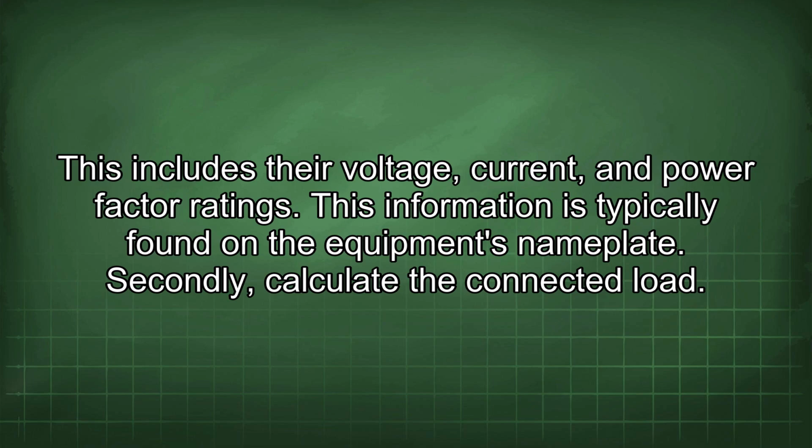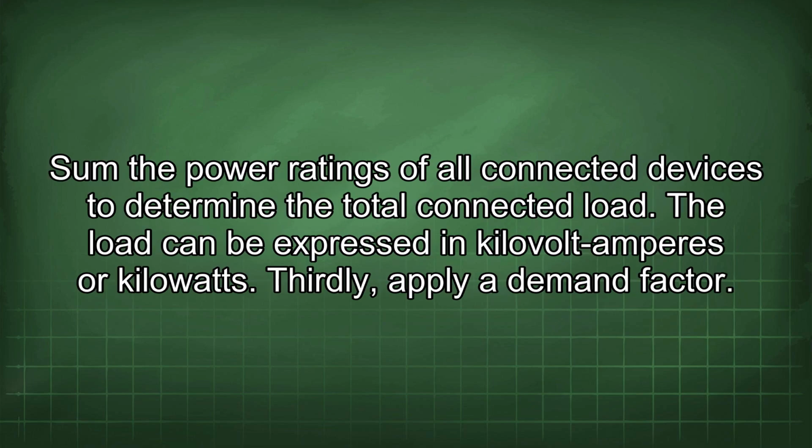Secondly, calculate the connected load. Sum the power ratings of all connected devices to determine the total connected load. The load can be expressed in kilovolt amperes or kilowatts.